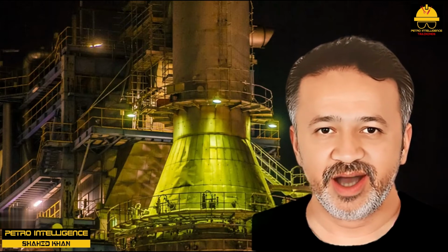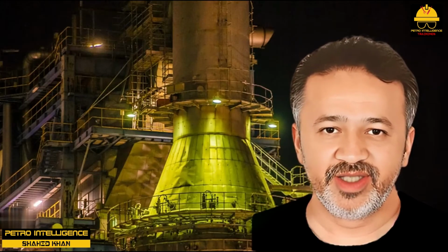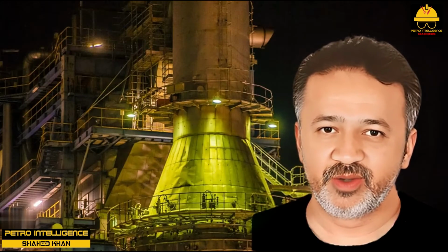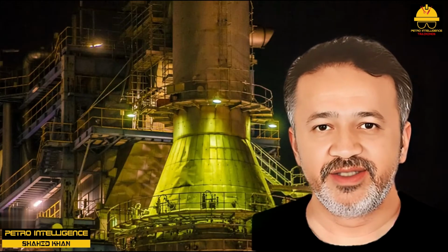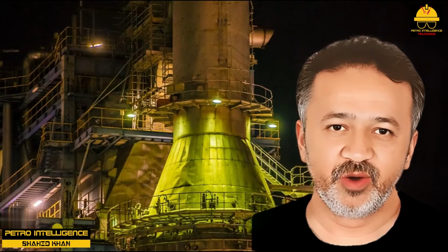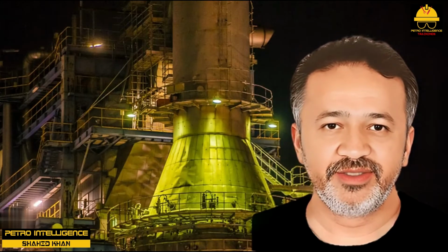Indeed, the oxygen content, %O2, of the flue gas typically varies in the range of 0.5% O2 to as much as 10% O2 depending on the design, mechanical integrity, and operating characteristics of the equipment, such as firing rate, burner type, and ambient weather conditions.